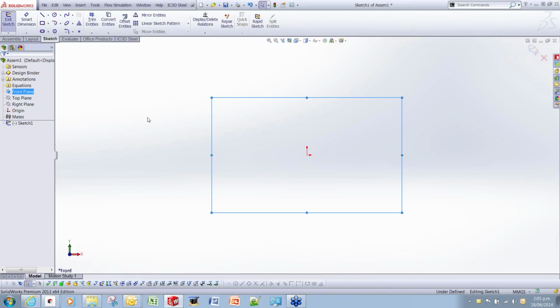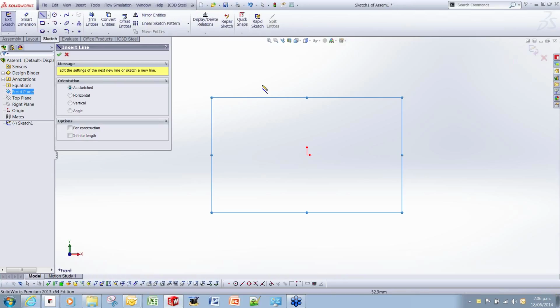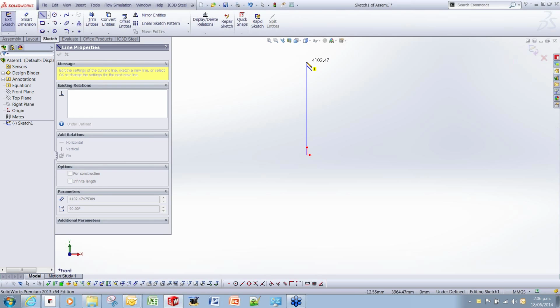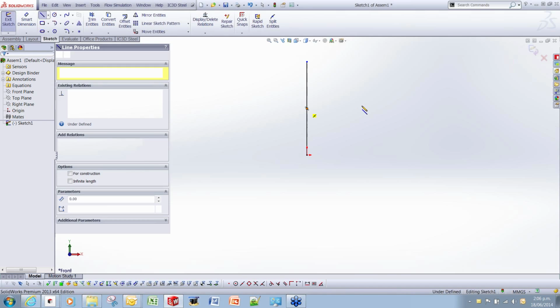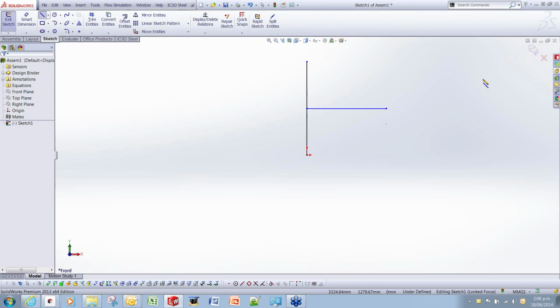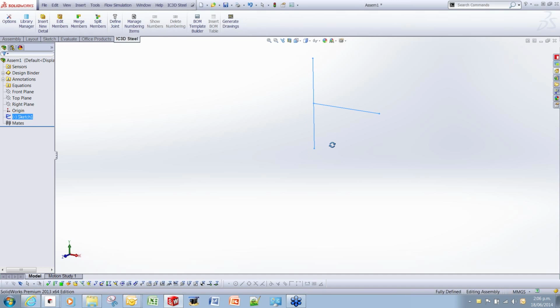So for those of you who are familiar with SolidWorks, you'll probably be familiar with the existing weldment functionality, which lives in the part environment and is very good for producing welded steel structures, but there's just no functionality in there for producing bolted steel structures. So what I'm going to do here is highlight the bolted connections that can be automated using 3D Steel. So the first thing to note is that we're working at the assembly level.